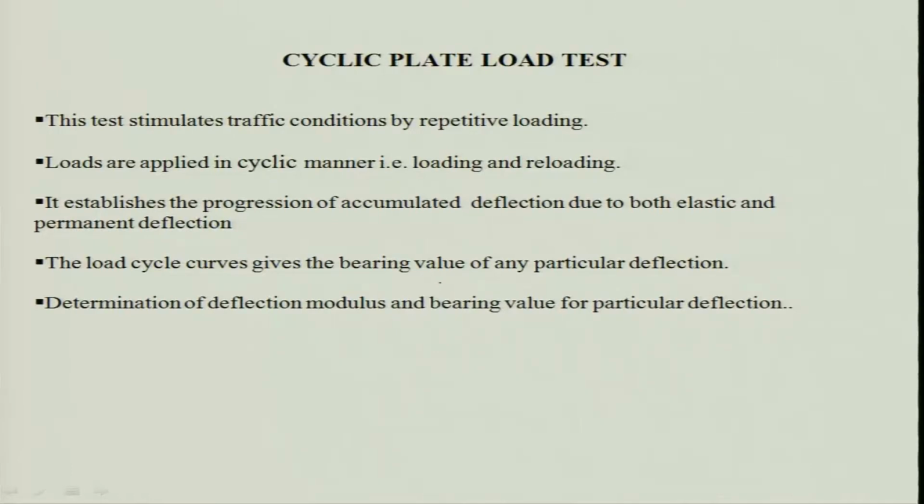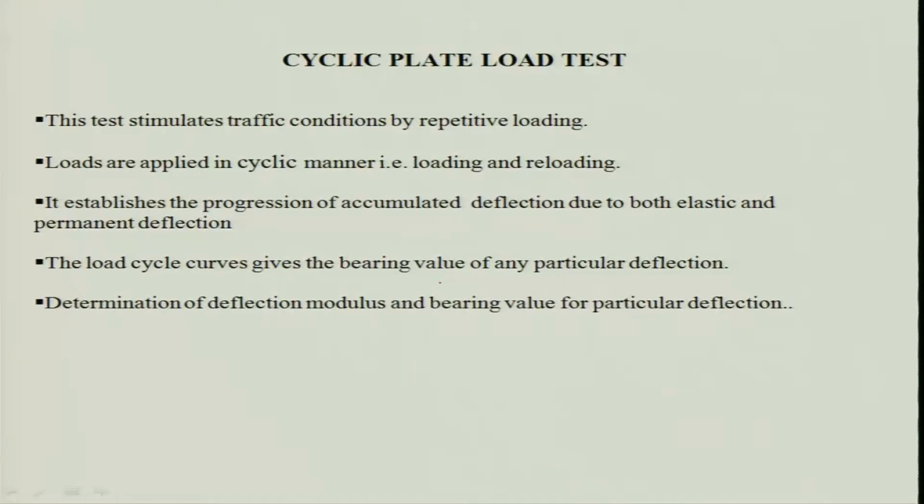There are also cyclic plate load tests. Cyclic plate load test of loading and unloading, why are you doing it? The test simulates traffic conditions by repetitive loading. Loads are applied in a cyclic manner, that means loading and reloading. It establishes the progression of accumulated deflection due to both elastic and permanent deflections. With cyclic loading you find out what your elastic settlement is as well as permanent; basically the elastoplastic behavior of the soil you can get.